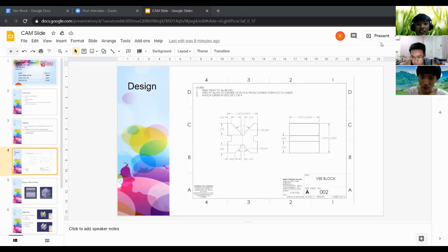After that, we'll start on doing the curve and the hole on each side. For the curve, for the upper part of the side extension, it will be 0.234. The curve angle will be 45 degrees. Here it would be 90 degrees, since we'll be taking half, as I mentioned, so it will be 45 degrees. By taking 45 degrees, we'll get the slant length. And then we take the hole.